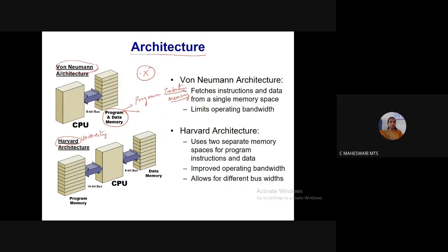What do you mean by instruction memory, Nadia? Yeah, it's where you're storing your instructions, right? When you start writing, you're storing instructions, for example, move A comma B, with the equivalent opcode, for example, 08H. So at memory location 4100, you're writing all these instructions, then 4101, 4102, you're writing 020B like this. So these are all called the instructions, which are nothing but the set of operations that the microcontroller has to perform.